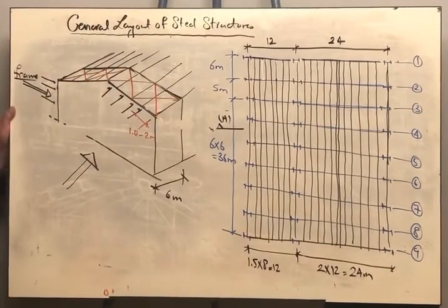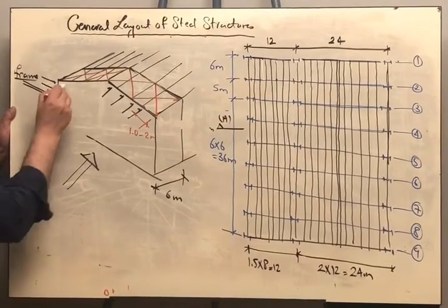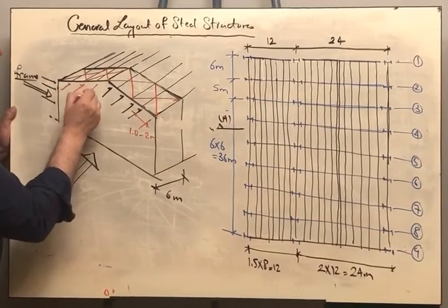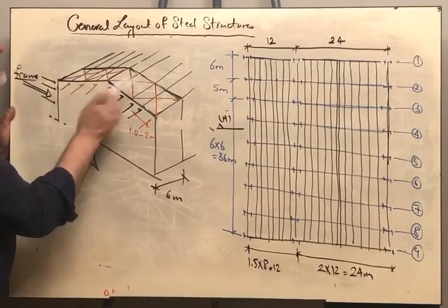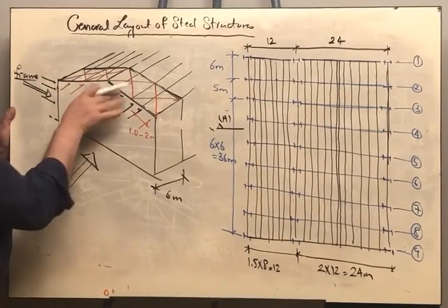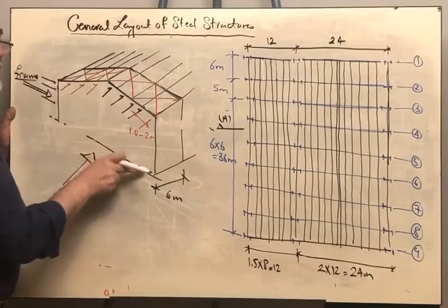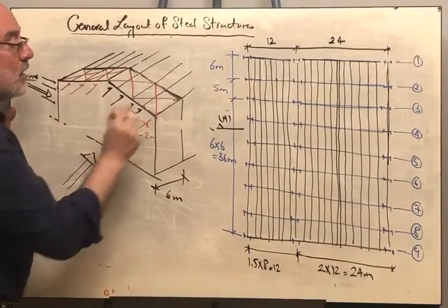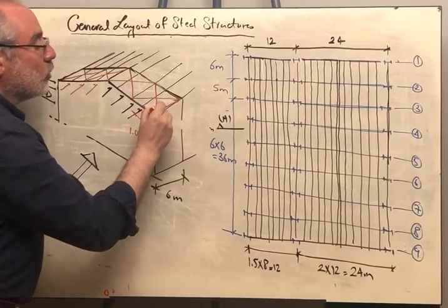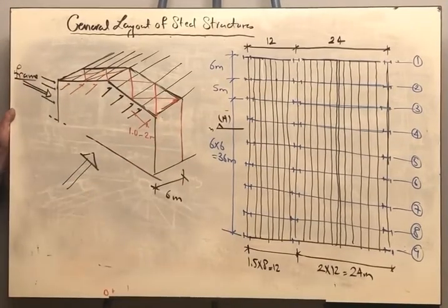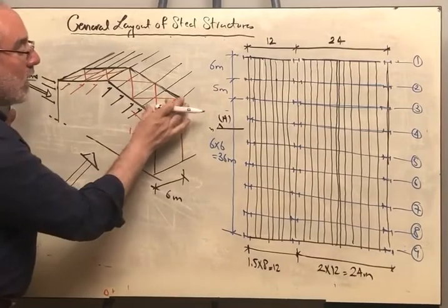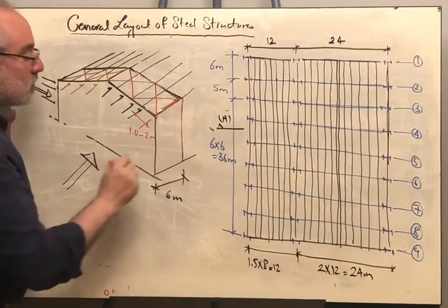Now we formed the upper bracing. Very good. When you are having forces applied out of plane, it will be taken by this truss. But where is this truss supported? It will transfer the force from the frame in the facade to the frame behind. Again, the frame behind cannot take this force because it is an out of plane force for this frame. That's why I will have to continue the bracing on the side.